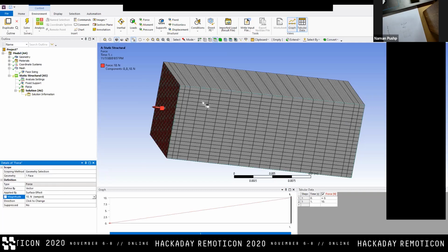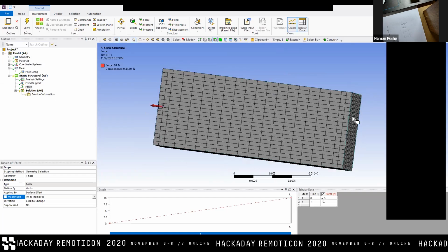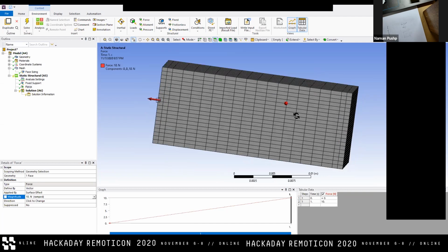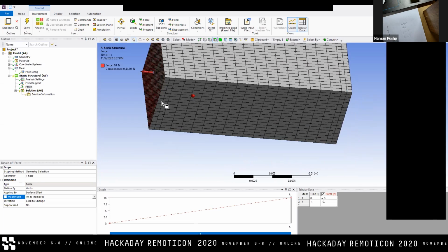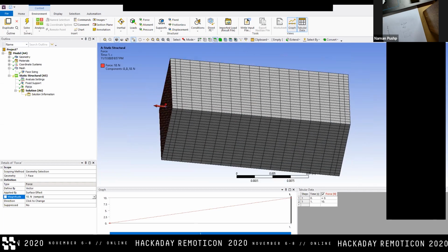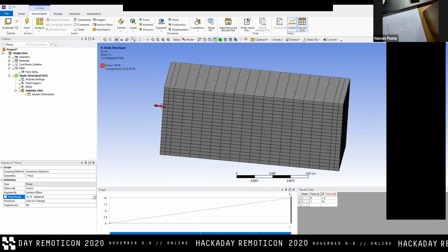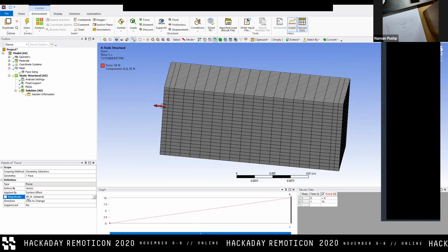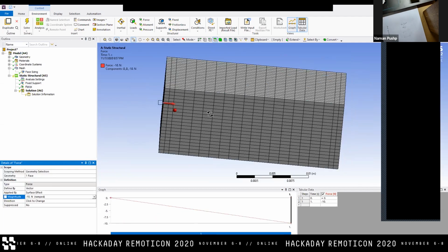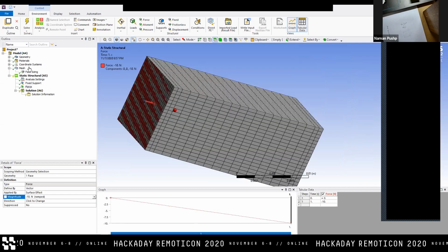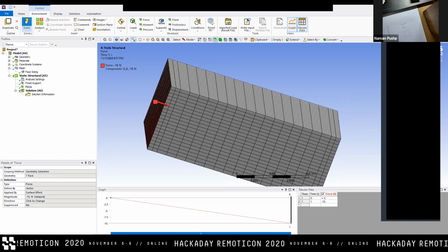Now that I've applied this force, that is the equivalent of me applying this force on both faces, because I'm keeping this one still. So the reaction force will always be identical. So actually in this case, you can see it's a tensile force. And I'm not sure if you guys can see the axes. Well, over here, because positive is this way, I would actually want to make it negative if it was a compressive force. And now it's a compressive force. So now I really have all of the information I need, and I can actually solve it directly now.